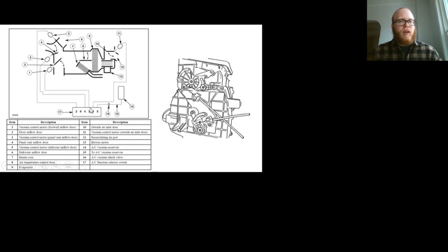This is a look at what a vacuum diagram would look like for a vehicle. You can see all the heavy hitters are there. We got the blower motor, our evaporator, our heater core. And the interesting thing is, even in those systems, the blend door was usually electrically controlled because it needed to have more than two states. It couldn't just be on or off. It needed to be able to be fully cold, medium cold, kind of warm, super duper warm, right?